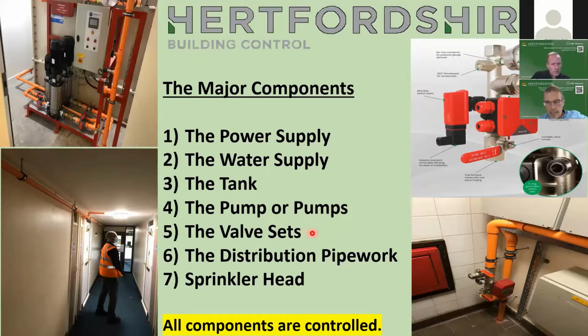The valve sets are now quite controlled in comparison to what they used to be. Obviously, there's lots of valves involved. There's a valve set there that you can see, and that's an isolation valve. And that's an interface back to the fire alarm, because the second that isolation valve is turned off, it'll send a signal to the fire alarm panel.